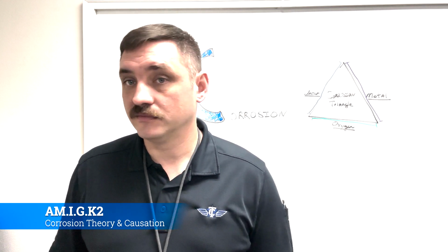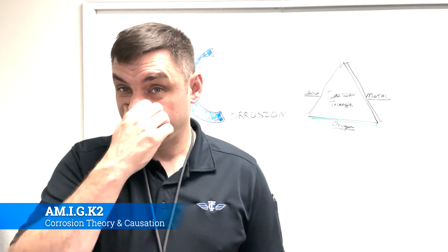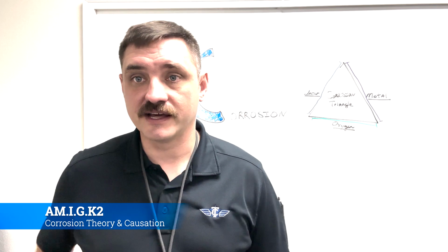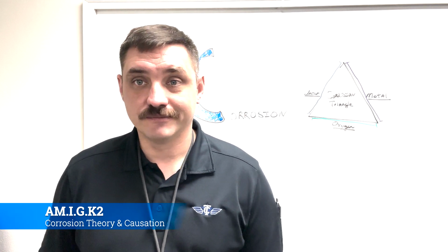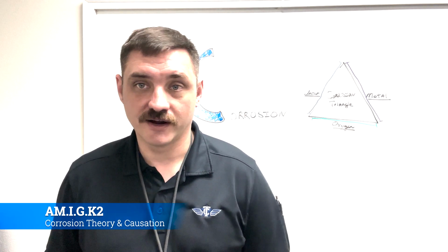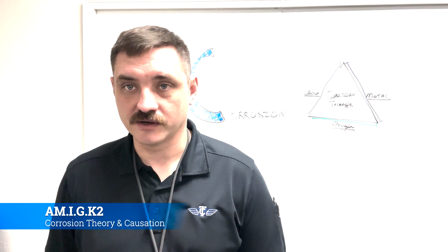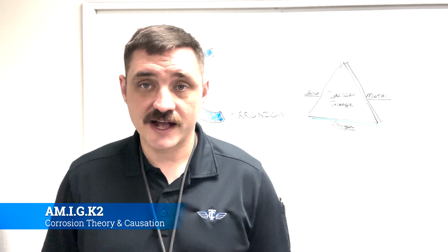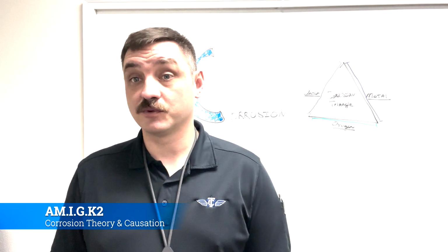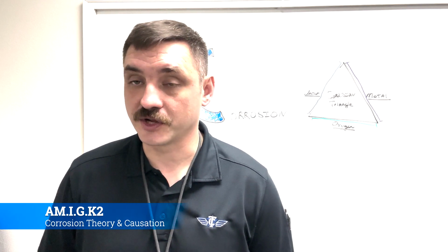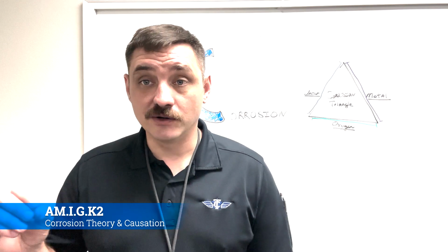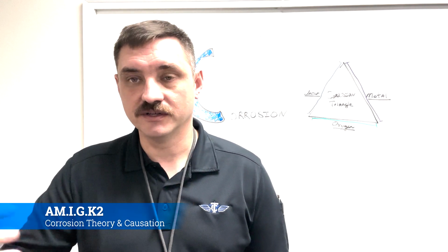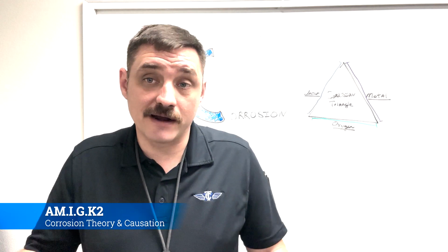You'll do any number of inspections if you're operating around salt water, seawater, anything like that, or in a water-rich environment, say a rainforest or whatever. You'll be constantly doing corrosion stuff. Now, where it mentions battery acid, it's a direct chemical attack, and that's one that can really ramp up the corrosion pretty quick, because the battery acid is built to be highly reactive and has a lot of electrons to get rid of. That's what its whole thing is. That's how a battery works.